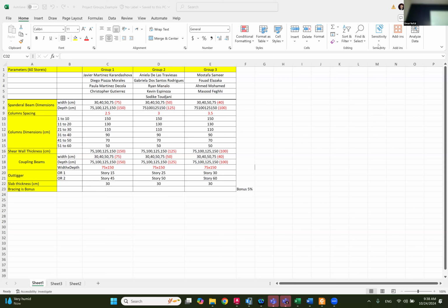Like in the analysis of any beam under gravity loads, the width is important, but the most important thing is the depth. That's what gives them more stiffness, because this is the dimension that is cubed. Do you remember the inertia of the beam? It's b h cubed, where h is the depth. It's to the power of three. The more you increase it, the more it is multiplied by the cube.